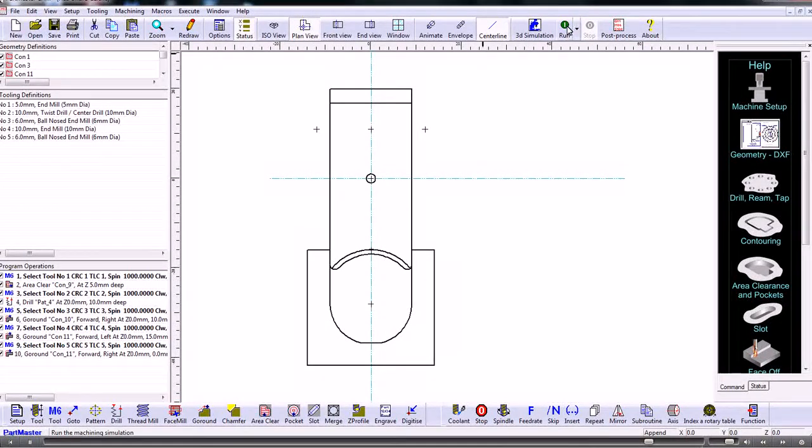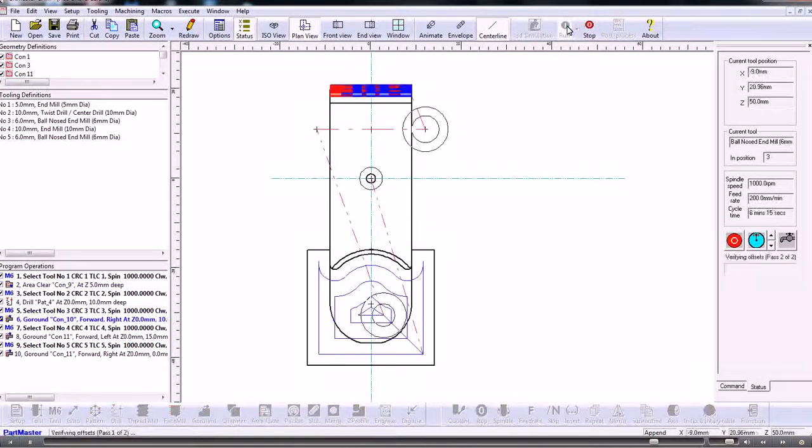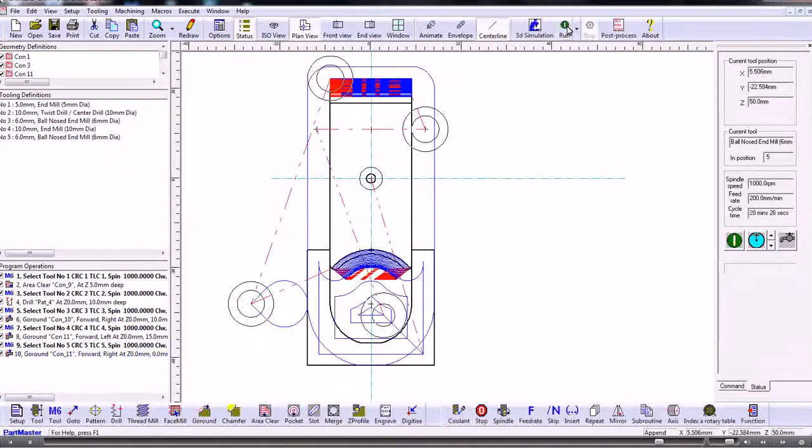And then that resets the datum. Any existing machining that you've got will just work on that newly set datum position. So it is something that you can change halfway through a job, or when you've finished a job you might need to reset the datum based on a new fixture that you're using. Okay, so that's how we do that.